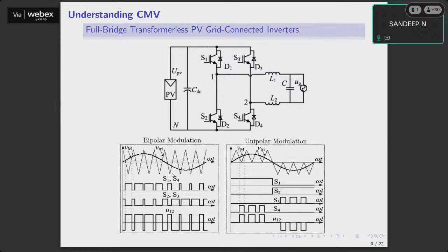That is where the overall idea of PWM comes from. By an on-off discontinuous function, we cannot have a sinusoid. So the best possible is to generate a waveform whose average value tracks a sinusoid.